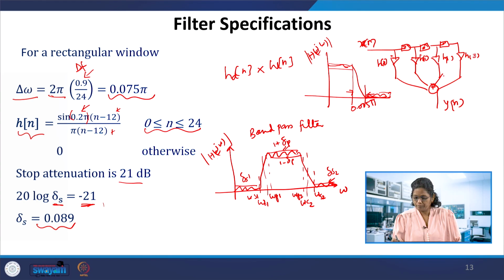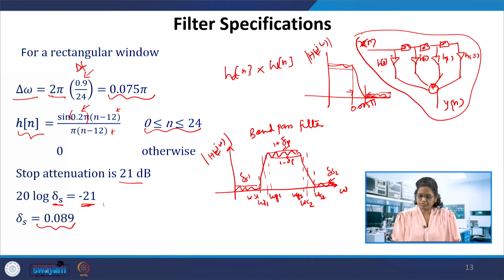How do we code this structure in Verilog? If you have a linear phase response, h0 and h3 are the same, and h1 and h2 are the same. So how do we code this filter structure in Verilog?